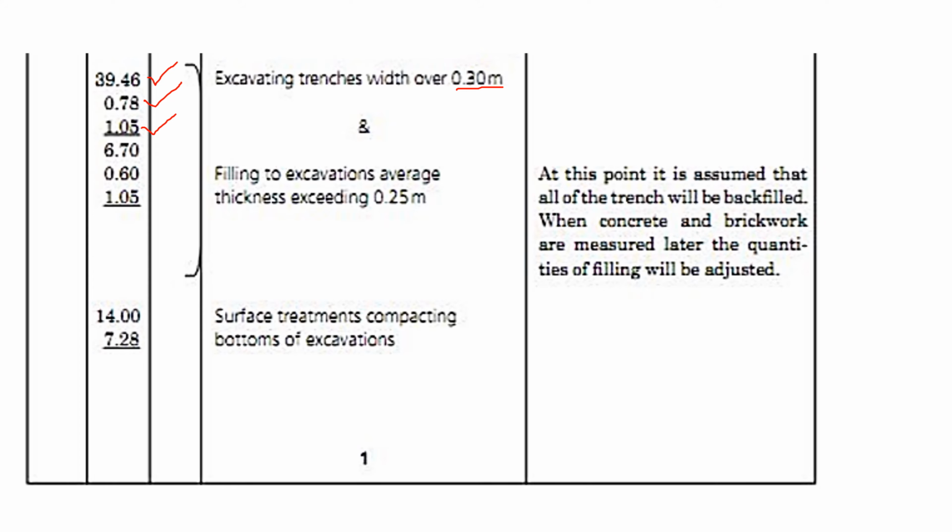The depth of excavation, you will take 900 plus the thickness of the concrete in the strip. Alright, for the internal partition, we shall take the center line, we multiply by the width of the internal strip footing, then we multiply it by the depth of the strip footing. So for all these, this will be the volume of soil where we shall excavate trenches.